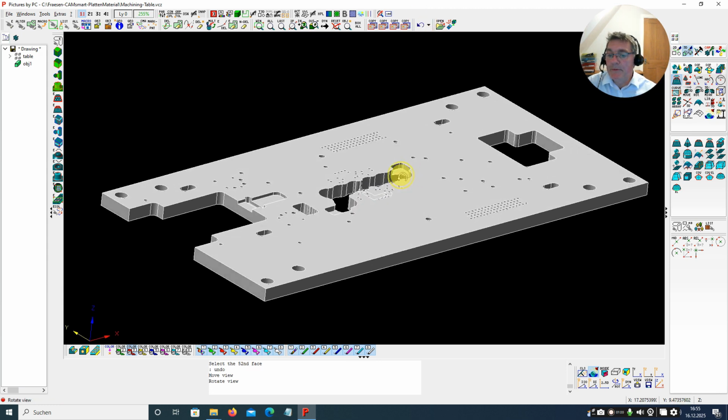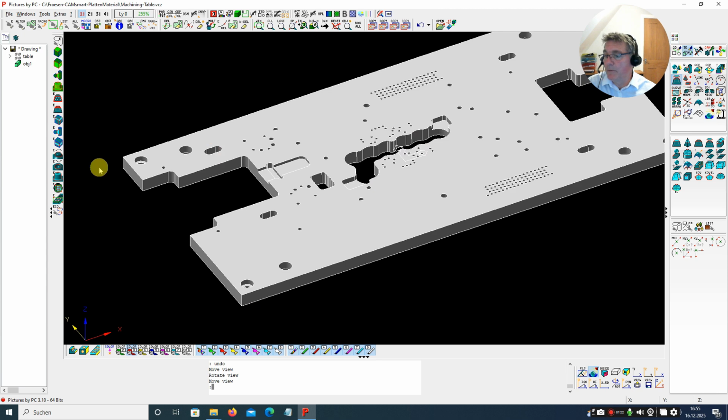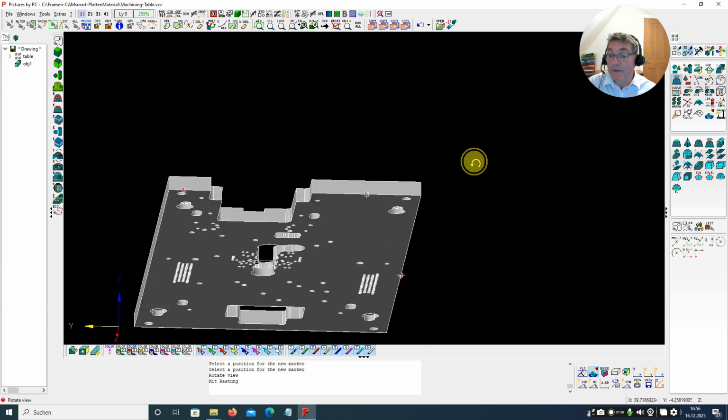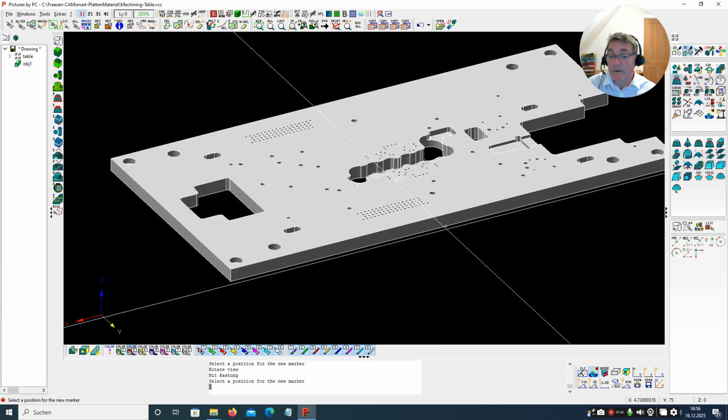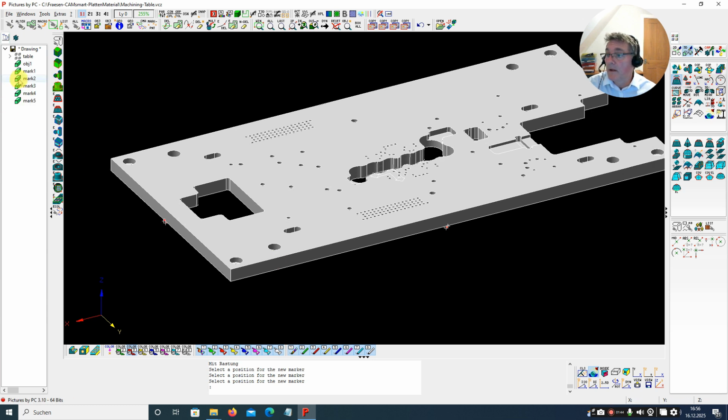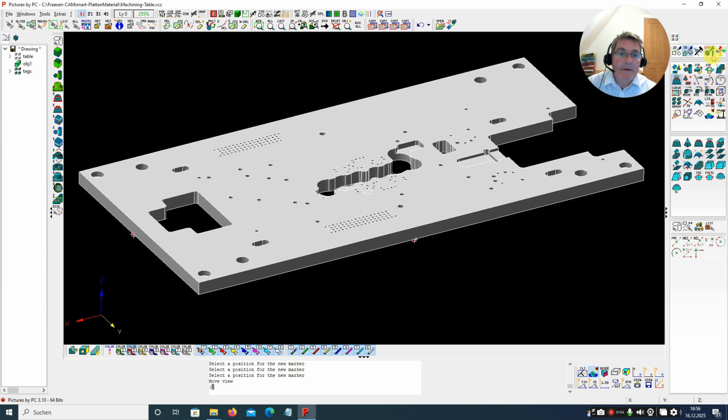So this is going to be machined from plate material. If it's on a vacuum table, we could profile around the side here, full depth, and the part's going to stay in position obviously. If we didn't have a vacuum table, we'd possibly need to tag this. So I'm just going to quickly interactively position some tags. The software can do this automatically, so create a set number of tags along a profile or with a set distance. Those point markers for the tabs we're just going to group together and give a new name. Okay. And then let's look at the automated machining.